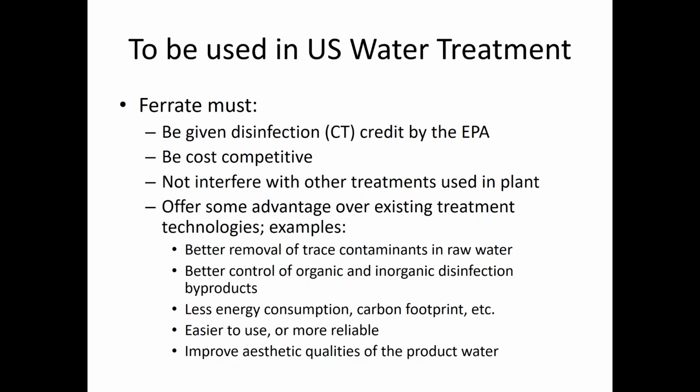And probably the single most important is that the U.S. EPA has not evaluated ferrate yet for disinfection credit. And so in other words, it doesn't have a set of CT tables that you can use to get credit for it. And so even if you use ferrate, and even though it's a good disinfectant, you still need a conventional disinfectant to meet regulations. In that regard, EPA is starting to look at and has been working with us to develop design parameters for developing a CT table. And so that may change in the next few years.